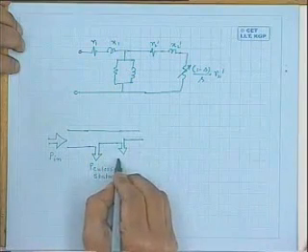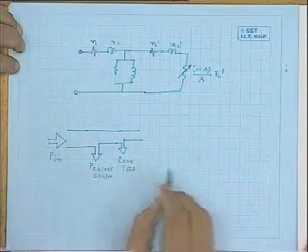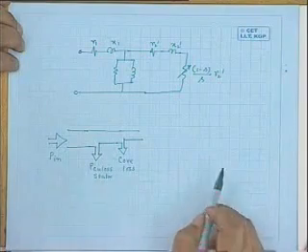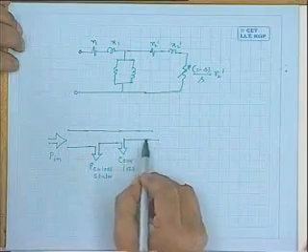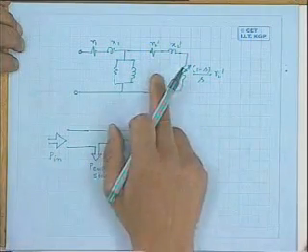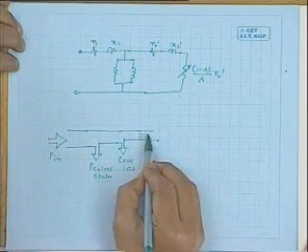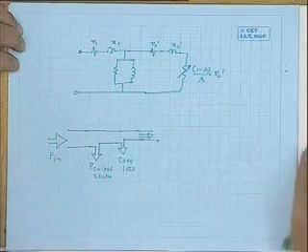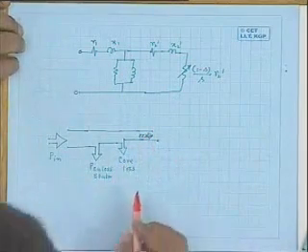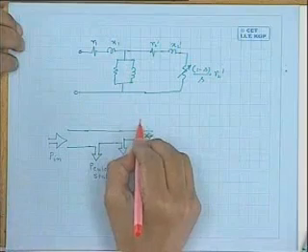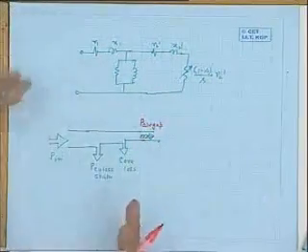Then the core loss is subtracted from this. That is the power flow diagram I am trying to visualize. Now from this, what else do we have to subtract? The rotor copper loss. Now at this level, this power is given a name. That is, after subtracting the stator losses, this power is called the air gap power.